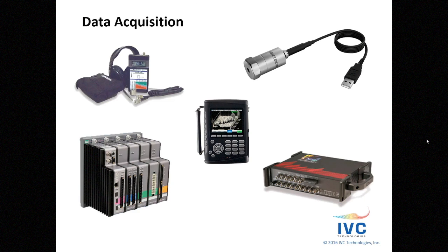Data acquisition. Again, do I have the right data acquisition that I need? You can have something simple like this little overall meter. In this case, this top right one is a digital transducer where all the electronics to record the vibration, digitize it, and send it over via USB to a computer is all in one clean package.